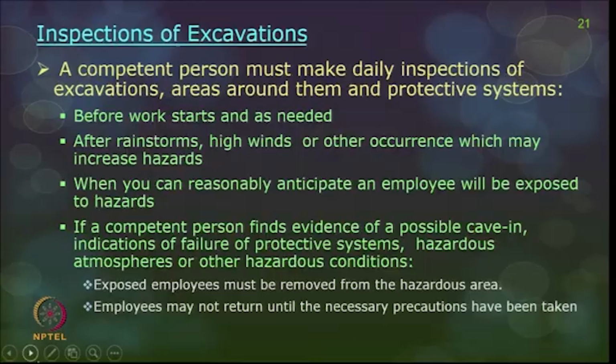Now, you have to do inspections of excavations as the excavation work is going on. So, a competent person, a site engineer or site supervisor, has to make daily or periodic inspections on the work. Under certain circumstances, he has to do this inspection regularly before the excavation starts, and as and when it is needed, maybe after a heavy rainfall or after an incident or an accident, you have to really check the site conditions. After rainstorms, high winds or other occurrences, you may have to do the inspection.